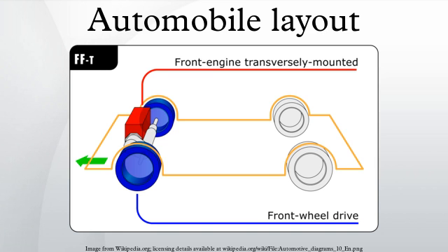The handbrake cannot be used to induce oversteer for maneuvering purposes, as the drivetrain couples the front and rear axles together. To overcome this limitation, some custom-prepared stage rally cars have a special mechanism added to the transmission to disconnect the rear drive if the handbrake is applied while the car is moving.